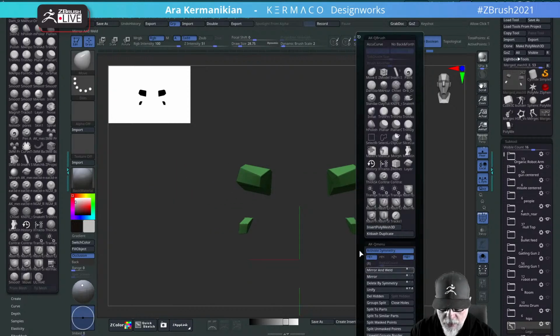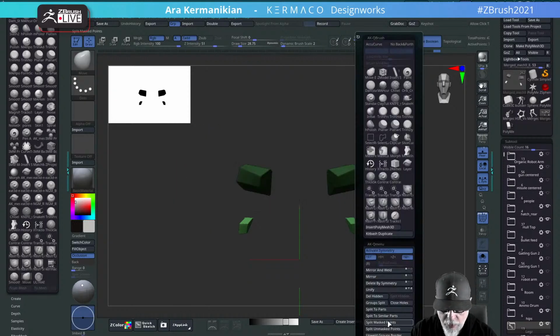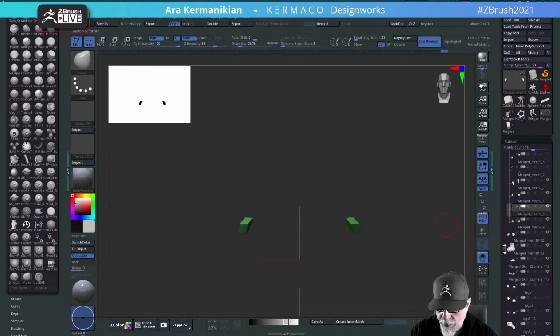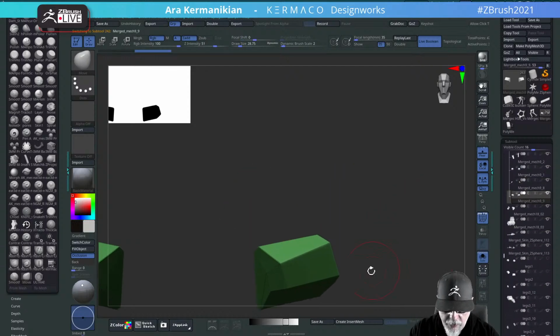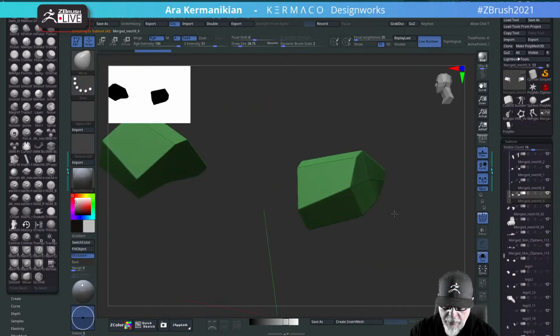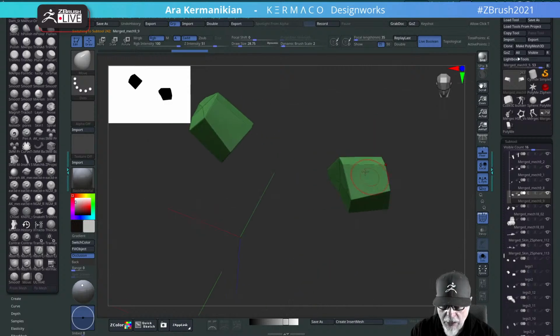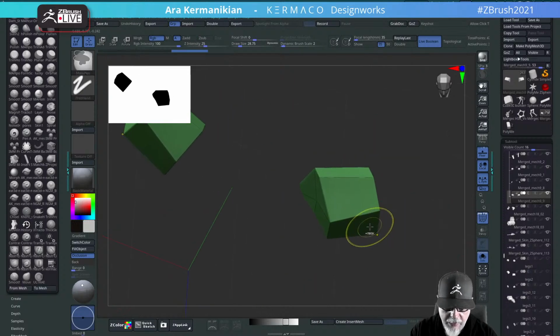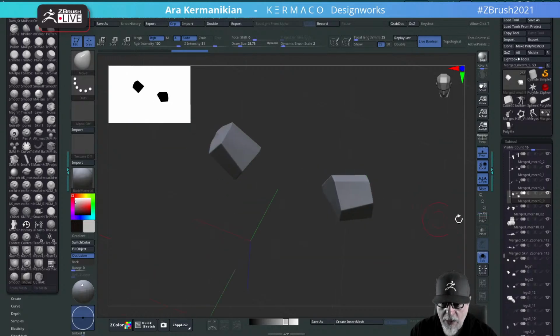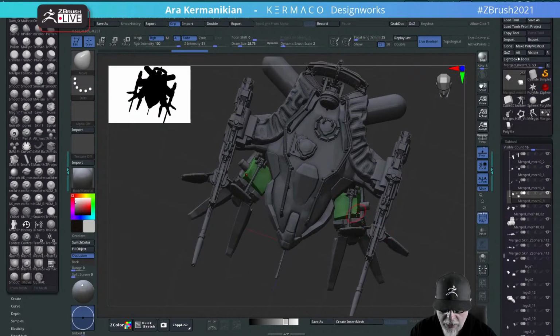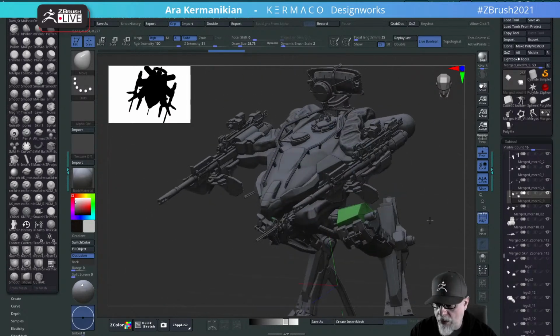I should split this. Let me mask this, split mask points, and go to those points over here. So as you can see here, these are pretty low poly, right? So you definitely don't get a lot of wobbliness. Now, if I subdivided this a few times and then started moving these points around, then it would not look as sleek. So keep your geometry low for as long as you can, and then once you get the shape you want, you can add detail if you want to.